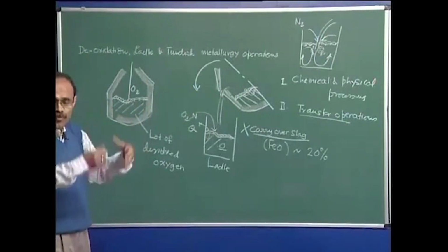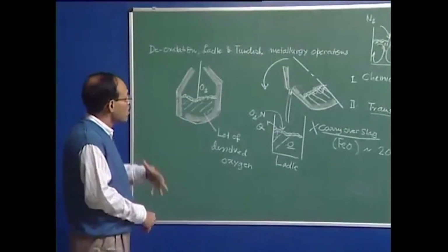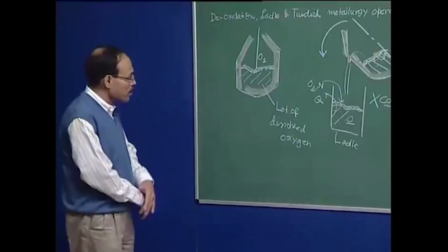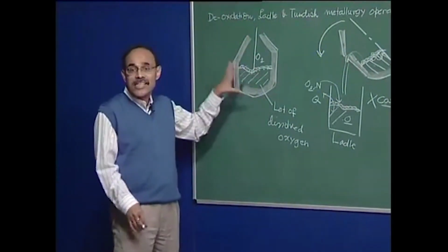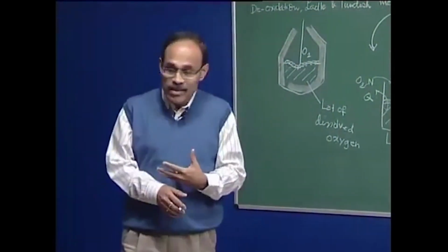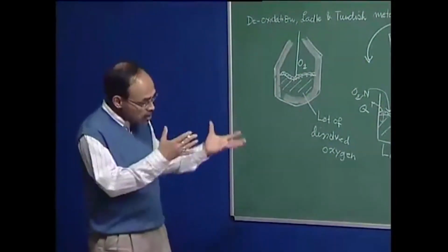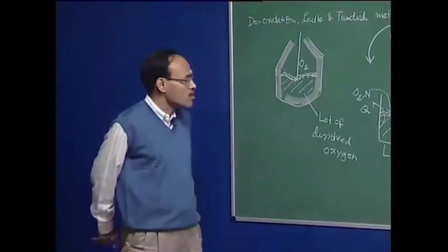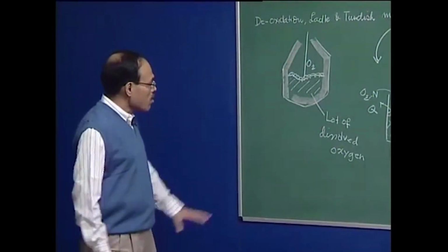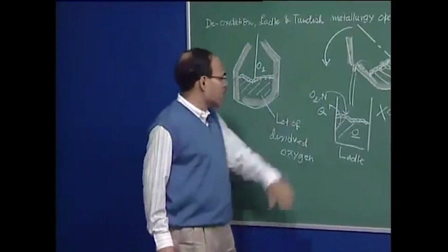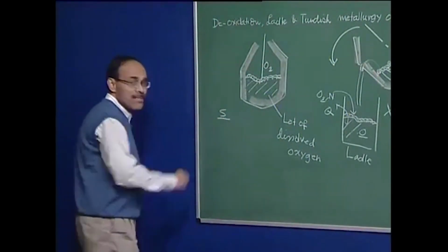for many subsequent operations, or an entire ladle metallurgy treatment station in steel plants, to adjust the composition and temperature of steel. And I repeatedly say temperature and composition. Composition is to meet the demand of the customer, and temperature because there's a stringent requirement on the part of continuous casting that the metal be delivered into the continuous casting mold at the right amount of superheat. So as primary steel making is over, we can assume that there is going to be maybe sulfur